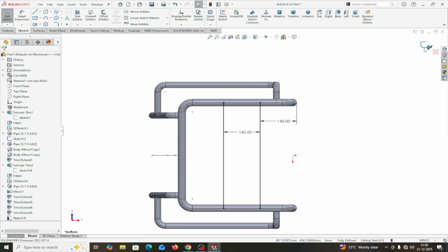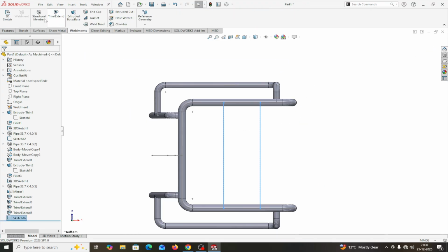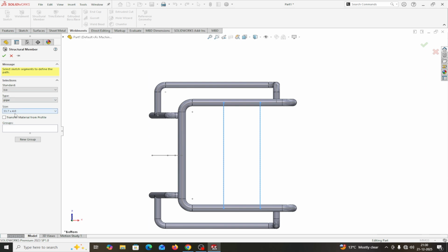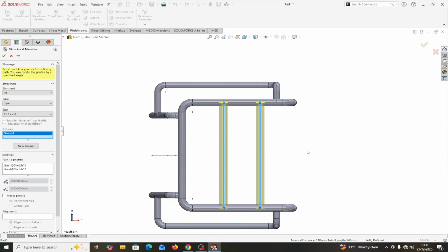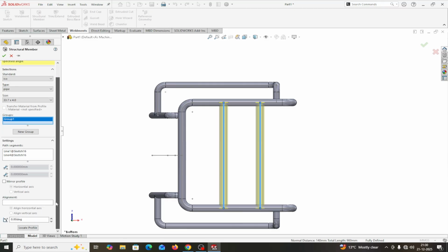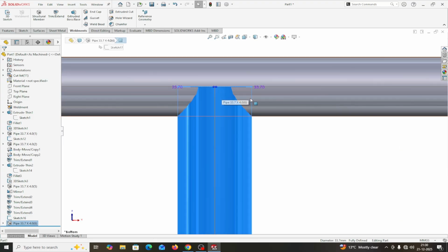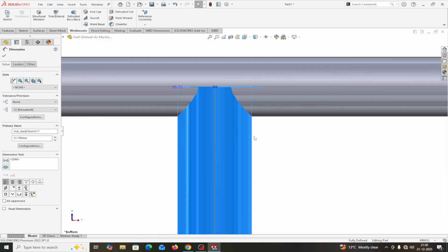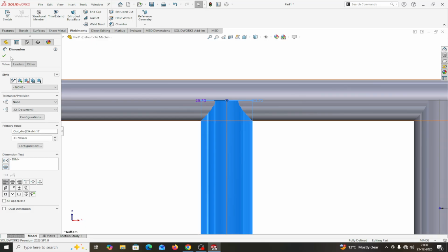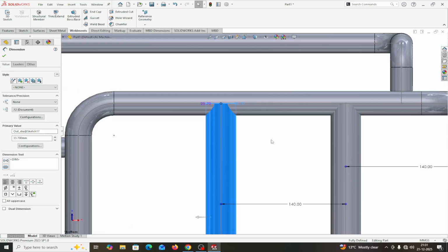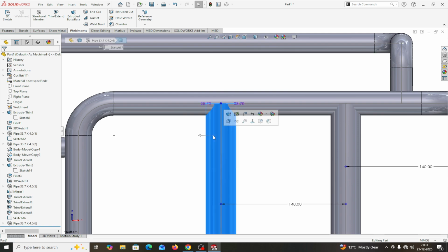Now out of the sketch, structure member. This one, this I will convert into a 30 mm pipe. This ISO standard circular pipe, this one, this and this one. Okay. Hit right button. Now you will see if I select this pipe, this is penetrating in this one. First you convert the pipe size. Select this.